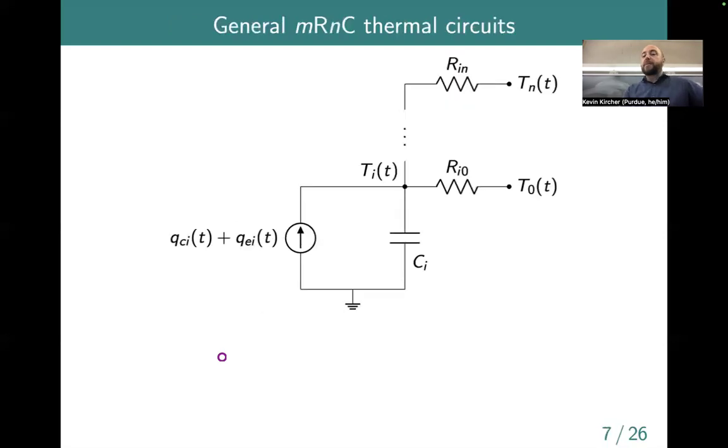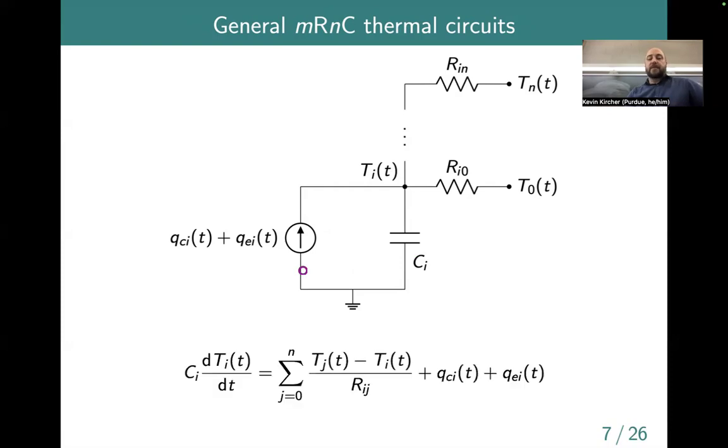And then we can play similar games with larger, higher order thermal circuits. So if you wanted to come up with one model that talked about the coupled temperature dynamics of this entire building, which might have 100 rooms in it, you might have a 100-dimensional or a 200-dimensional model, where maybe we have a thermal mass and an air temperature associated with each room in the building. And then there would be coupling between them. So here is kind of a general form.